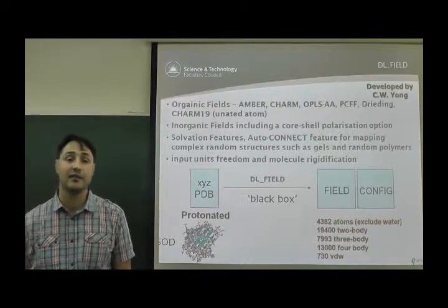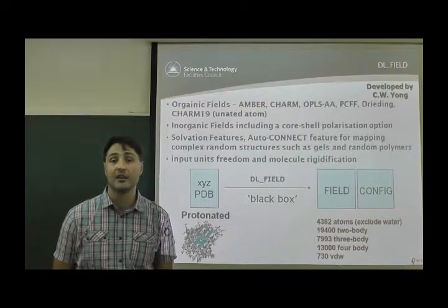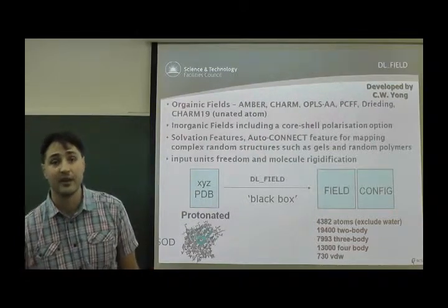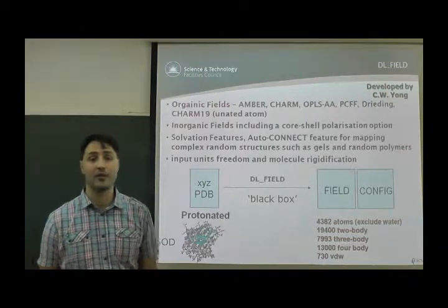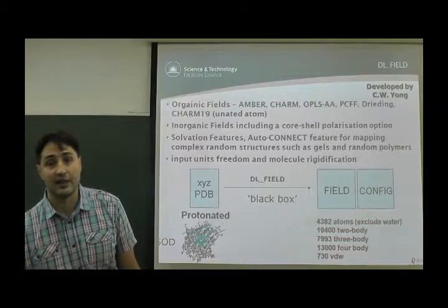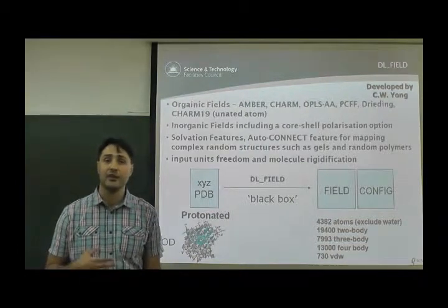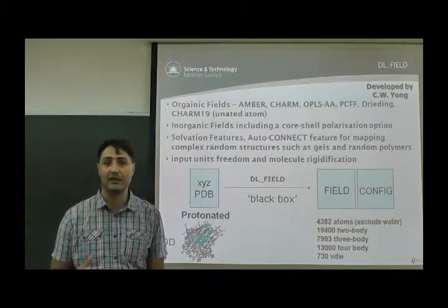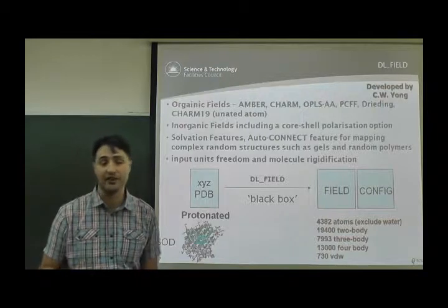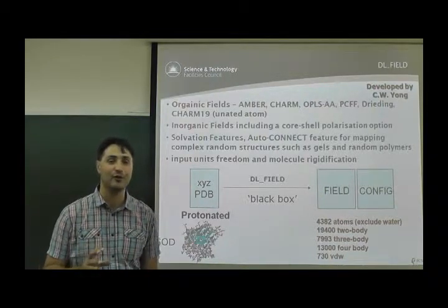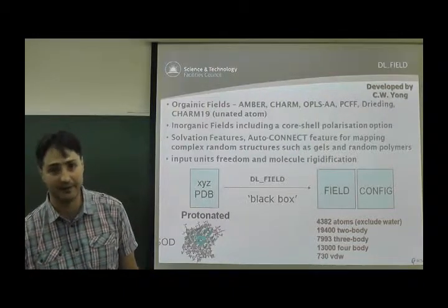Recently, we have included inorganic fields in the package, and it can account for core-shell polarization as well. There are solvation features and an auto-connect feature for mapping complex random structures, such as gels and random polymers. And of course, there is some input unit freedom and molecule rigidification if the user wants to use specific functionality of DL_POLY that is not usually default when you transform from PDB into DL_POLY format.